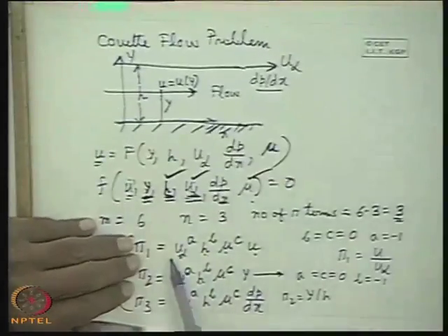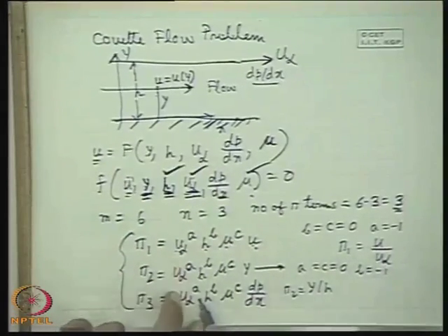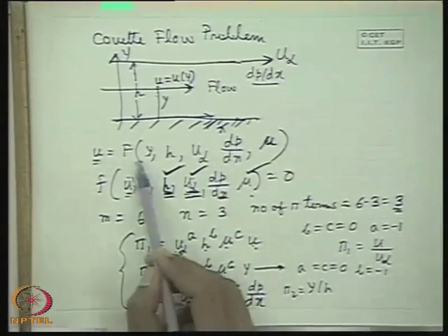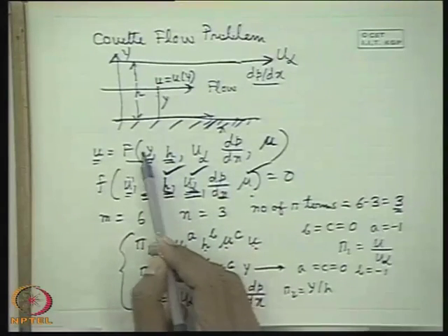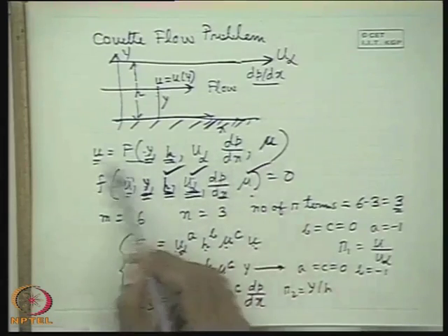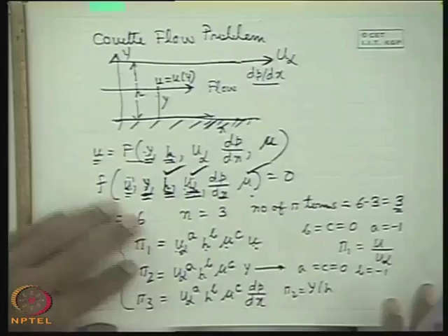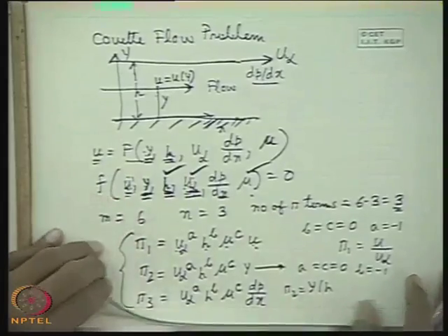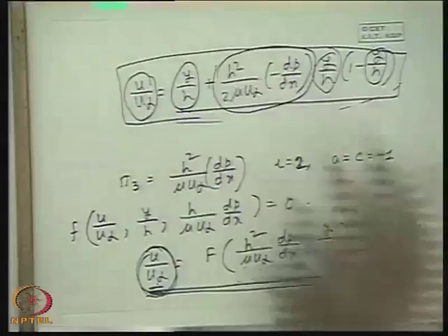So therefore, one of the conclusion is that if two terms having same dimension, their ratio is automatically pi term. That means in defining a problem, if I see there are two variables of same dimension y, h, so y by h will be a pi term. Similarly, two variables u here, u and u infinity are of the same dimension, u by u infinity is a pi term. So now I conclude the Buckingham's Pi-Theorem by telling this.